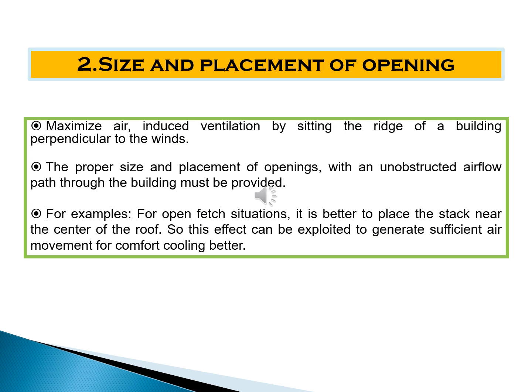Size and placement of opening. Maximize wind-induced ventilation by setting the ridge of a building perpendicular to the winds. The proper size and placement of openings with an unobstructed airflow path through the building must be provided. For example, for an open floor situation, it is better to place the stack near the center of the roof, so this effect can be exploited to generate sufficient air movement for comfort cooling.